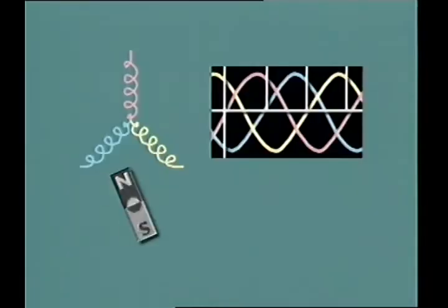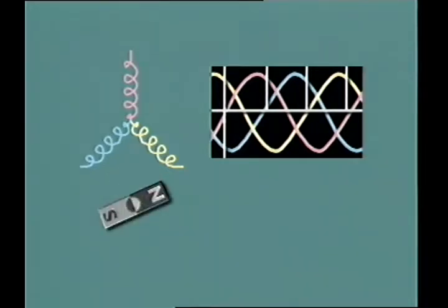In a real automobile alternator, three separate coils of wire or phase windings are common. The windings are arranged so that when the magnet is rotated, it generates a three-phase output. The phases are equally spaced in time, and this results in a phase shift of 120 degrees.